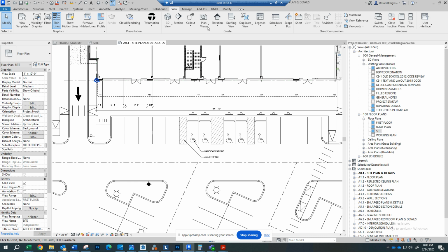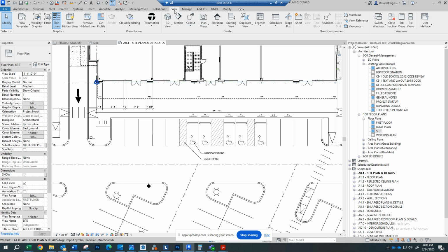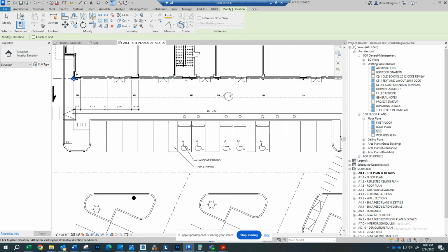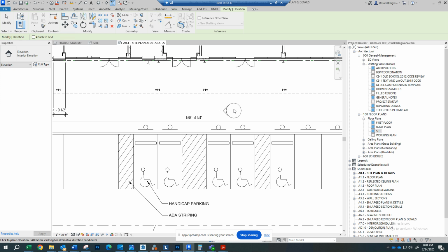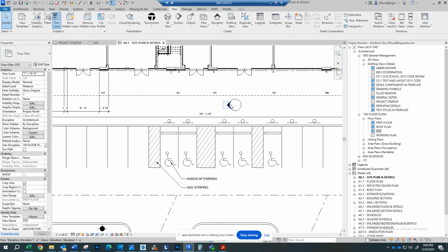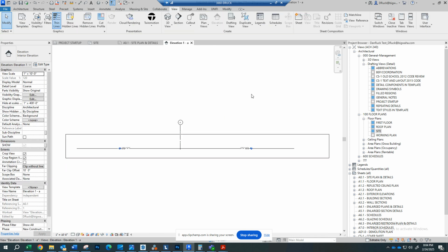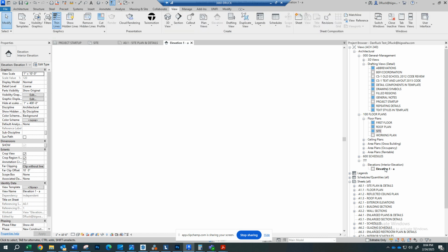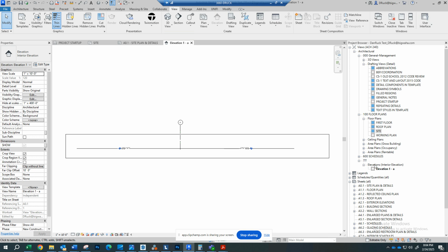But to briefly go into it, you can just click on View, hit Elevation, and you can see a little tool comes up, and there's a little caret head. We place it and click on that. You can see it will take you to a view. It will generate a view that will appear somewhere in your project browser, which it looks like it got placed under this elevations.